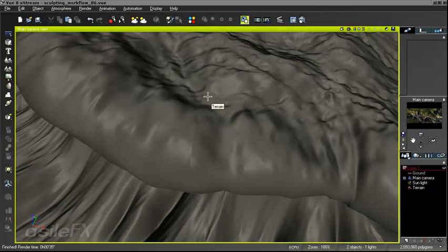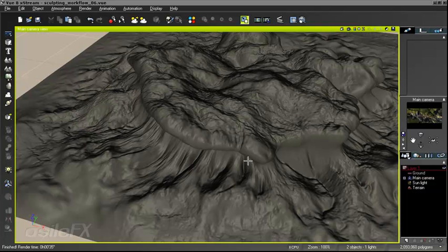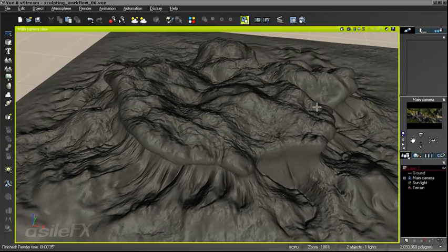If you are having problems with the division seam, where the sculpted displacement geometry and the pixel layer are separate resolutions, or the sculpted geometry layer has a lower polygon count than the pixel layer, one thing you can do to completely remove that seam that is showing up is to bake the terrain.